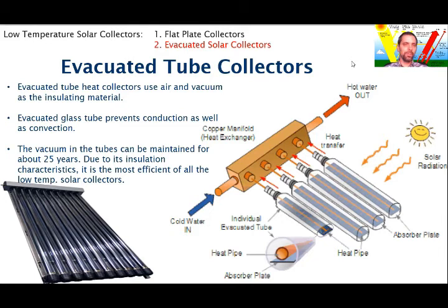Another advantage of these collector types is that they can operate at higher temperatures with better performance than flat plate collectors. An important feature is that their efficiency is higher at low incidence angles. In other words, in wintertime, when the sun is much lower than in summer, it performs better. And these types of collectors are becoming mass products, so for a lower price, a wider community can use them.